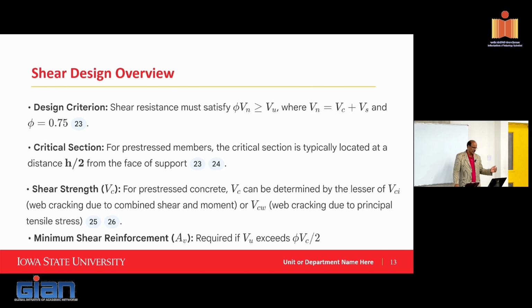Shear design, there's no surprise in shear design. Same process as what you do for reinforced concrete design. The only thing that you want to pay attention to is that the prestress itself actually benefits shear resistance quite a bit. Two ways, right? One is it keeps the crack width lower, so the aggregate interlock is going to be better. If you take reinforced concrete versus prestress, both subjected to the same load, let's say both are going to crack, the crack within a prestress beam will be smaller, and that's going to improve the aggregate interlock, so therefore you'll gain from it.